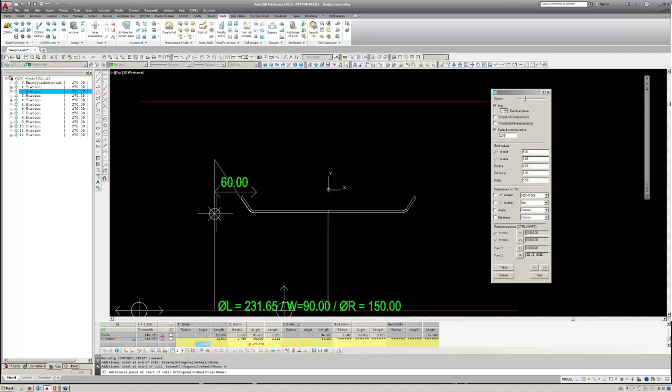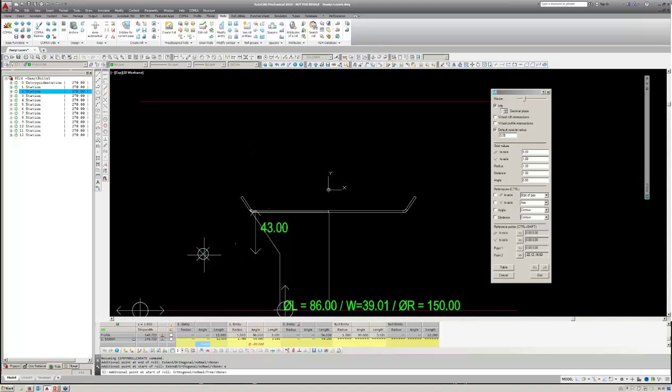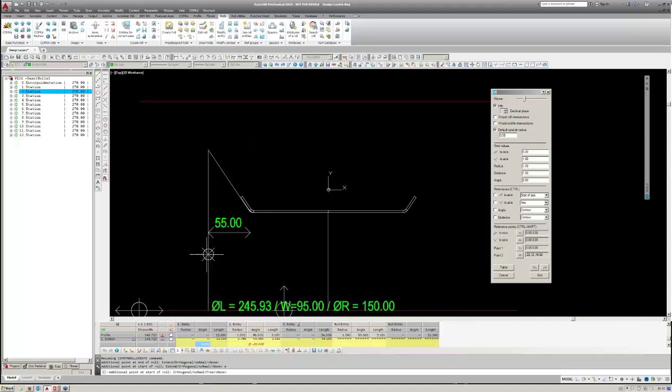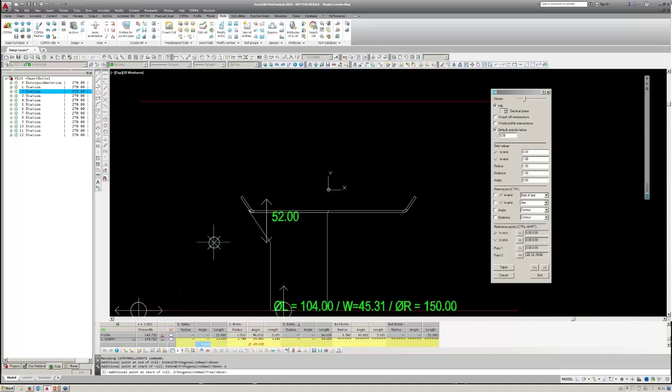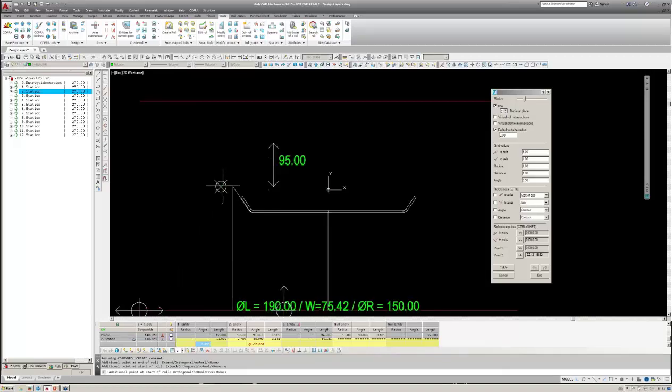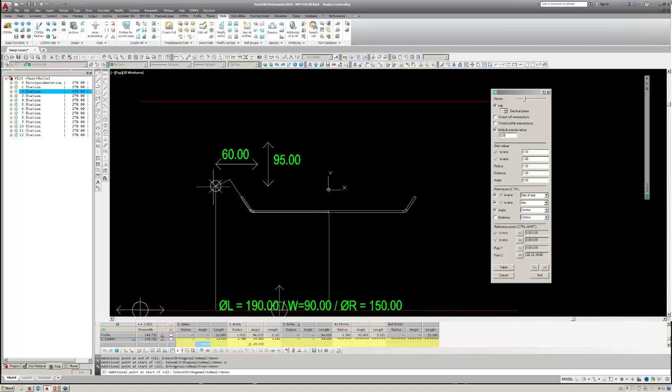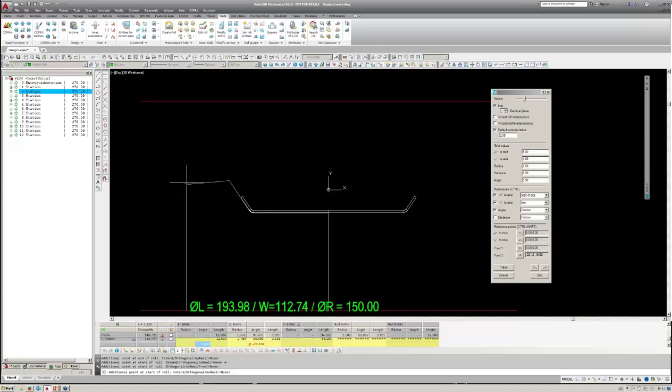If I move the marker down here to the underside, you can see I'm referencing the start of the axes as well, so I can use either or. I want to use the diameter, so I'm going on the top here, for a 100 radius, so that will be 200 diameter, as you can see. And this, as I said, is all visible because the info tick box is there. So now I go to left mouse pick, so there's my 100.